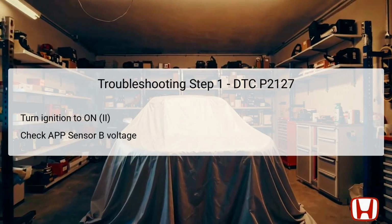The first troubleshooting step involves turning the ignition switch to the on position, also known as position 2. This action serves as a preliminary setup that allows various vehicle systems, including the APP Sensor B, to power up and function correctly. Using the HDS, Honda Diagnostic System, the technician will check the voltage output of APP sensor B.